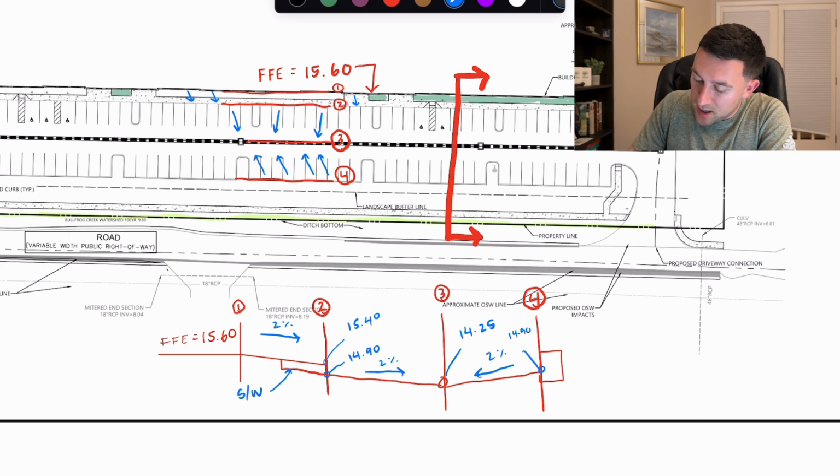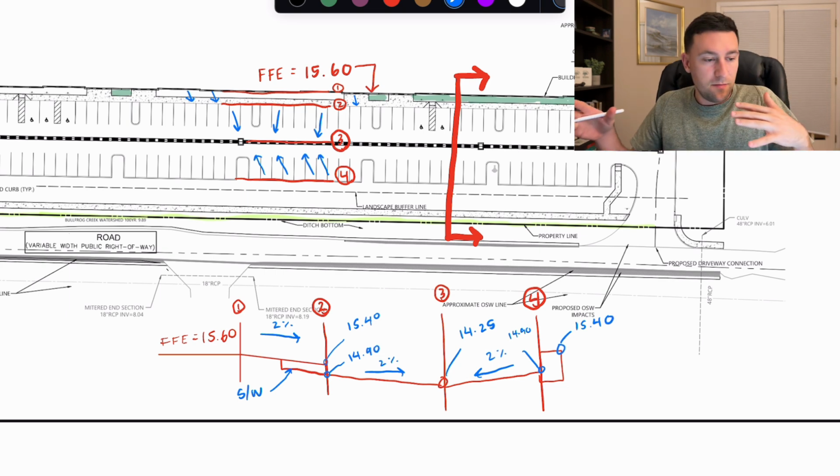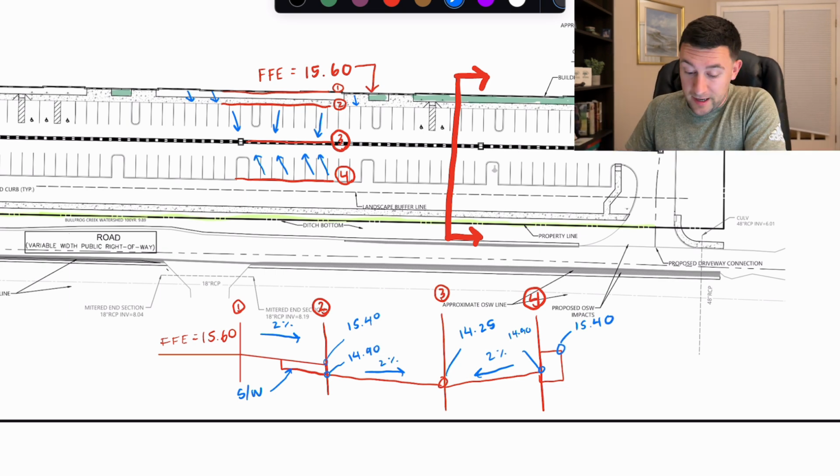So that means that this top of curb right there is going to be half a foot higher than 14.9, which if y'all are starting to draw these connections, it's the same thing as this sidewalk over here. So that grade is 15.4. So this thing is really symmetrical here. I could have done that really quickly just knowing the distances between these lanes, but I wanted to show you how I'm thinking through this.